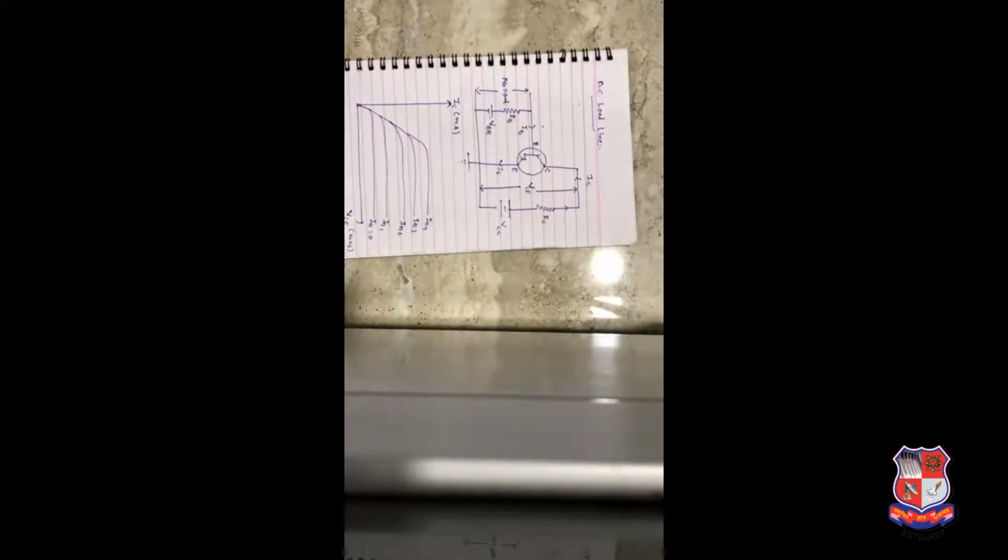Before going to the explained concept, what is the DC load line? There is one point on the y-axis and one point on the x-axis, and you have to connect those two points. Whatever line you find, that line is known as the DC load line. Suppose I assume this point A is over here and this point B is over here. I connect these two points and the line I get is known as the DC load line. One more thing, I told you that there is a Q point, and that Q point is present on this DC load line.